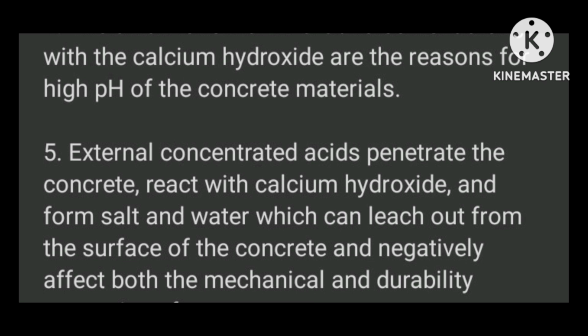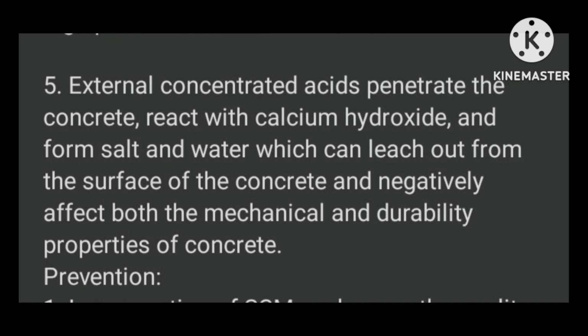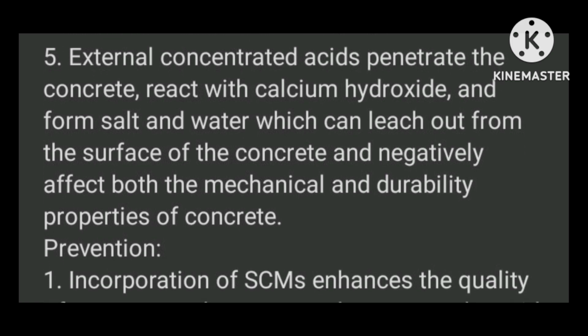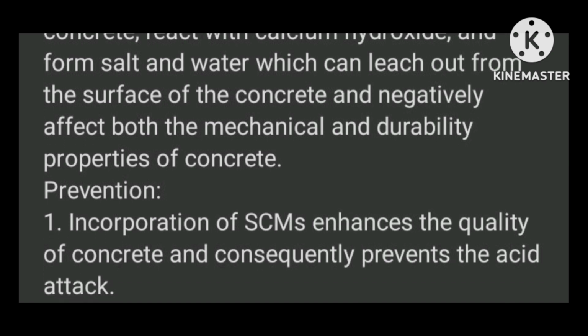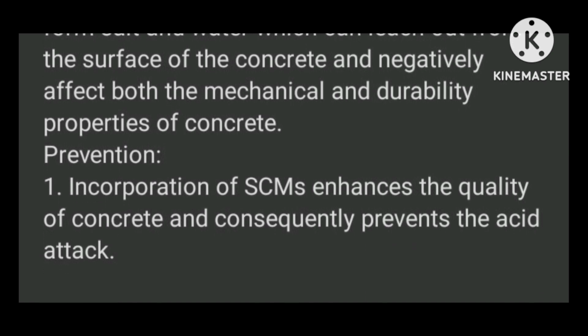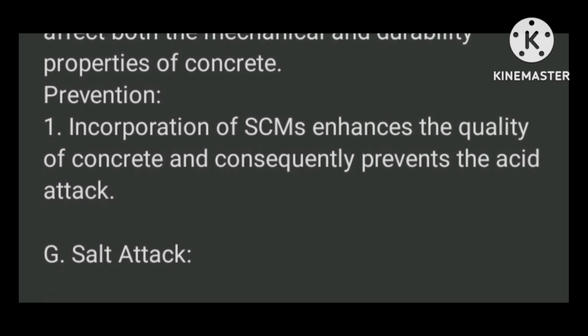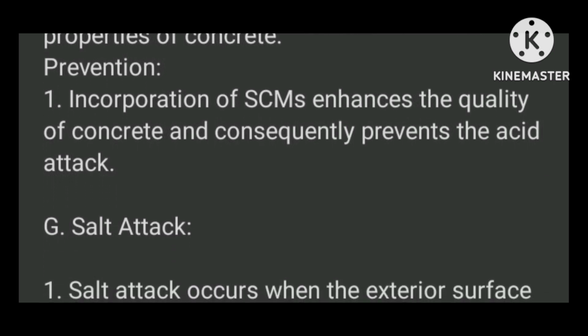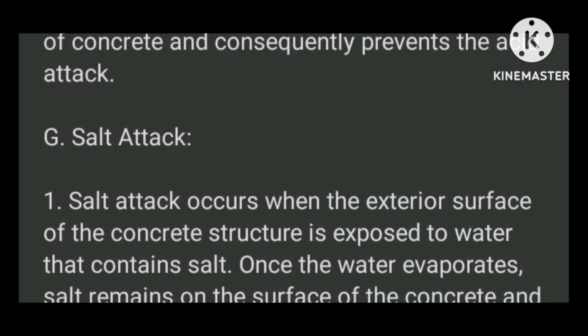Fifth, external concentrated acids penetrate the concrete, react with calcium hydroxide, and form salt and water, which can leach out from the surface of the concrete and negatively affect both the mechanical and durability properties of concrete. Prevention. First, incorporation of SCMs enhances the quality of concrete and consequently prevents the acid attack.